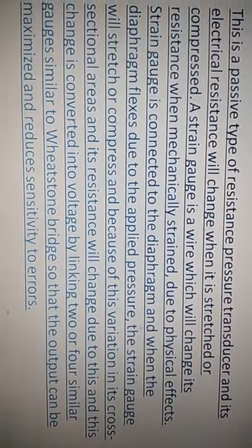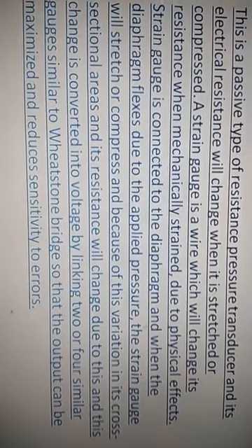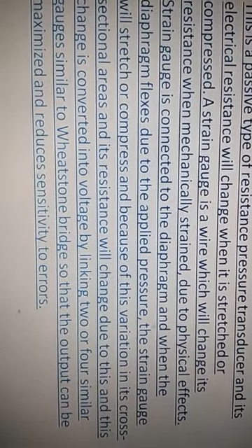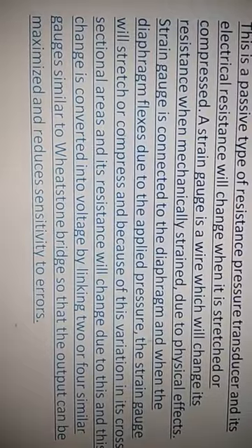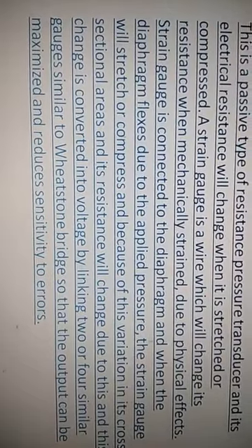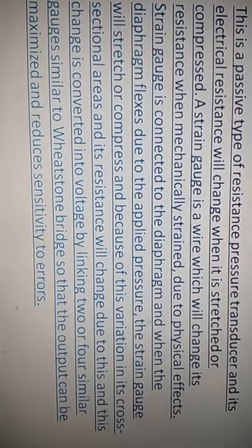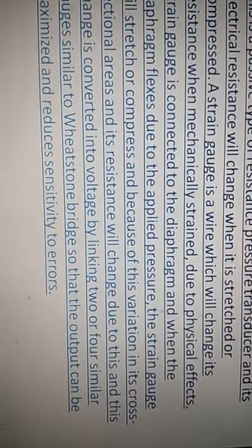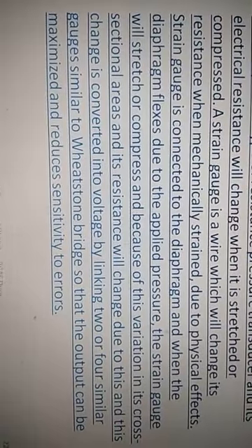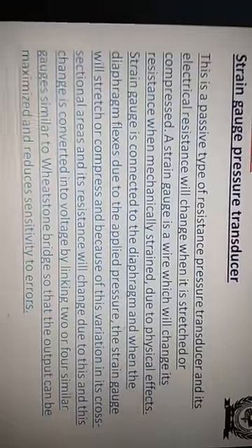This change is converted into voltage by linking 2 or 4 similar gauges in a Wheatstone bridge, so that output can be maximized and sensitivity to errors reduced.